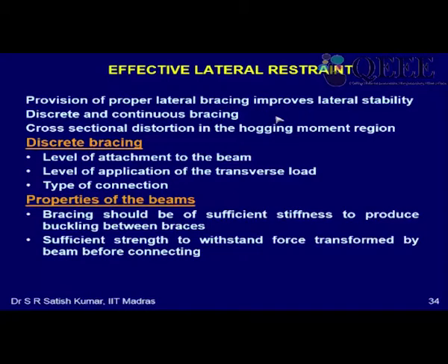So what they do is, if you find that two beams which are running parallel to each other, both are laterally unsupported, and I want to support them, I may want to give plan bracing, okay, between the two beams. So this plan bracing will ensure that the beams cannot deflect laterally and they get supported. Okay, so this is called discrete bracing. That is, it's not continuously braced.